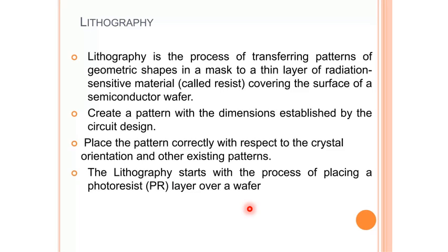It is the primary method for defining the areas of interest, that is, where we want the material to be present or absent. So these areas of interest are getting patterned through this photolithography process. So the first step of this is that the wafer is to be coated with the photoresist and subjected to selective illumination through this mask. That is another name, photomask.